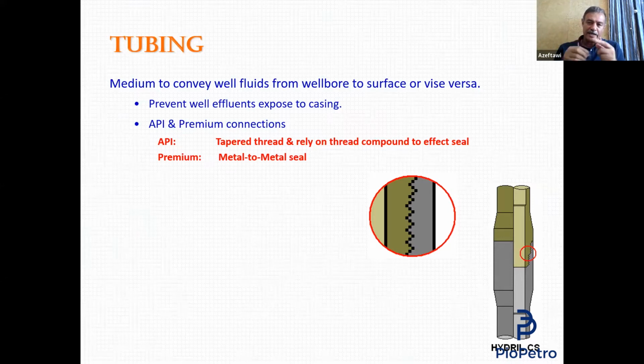If you put this one layer and you connect, then use the spanner to tighten, pressure test. If it is still leaking, that means the wear that happened to the thread is beyond repair. So what you should do is disconnect it, kiss it, and say goodbye. Throw it in the garbage.